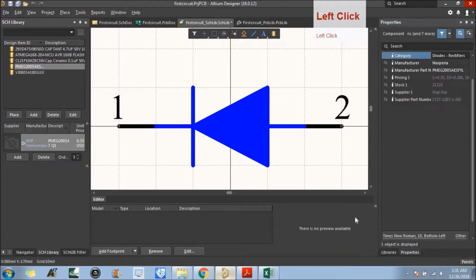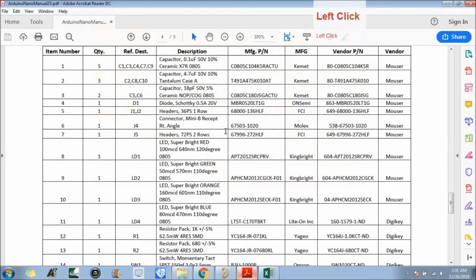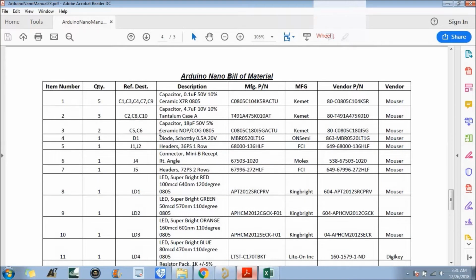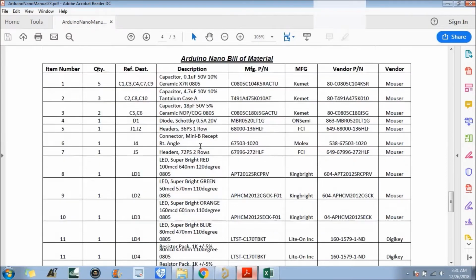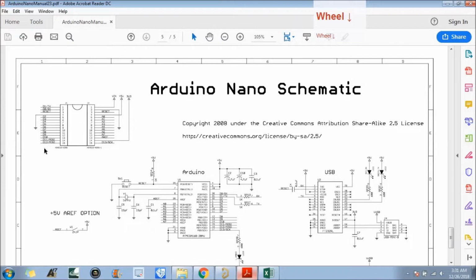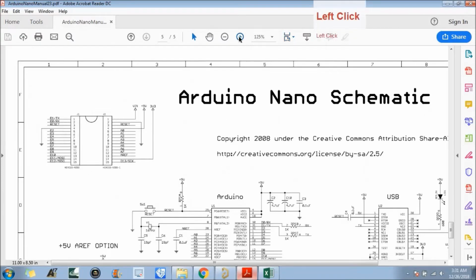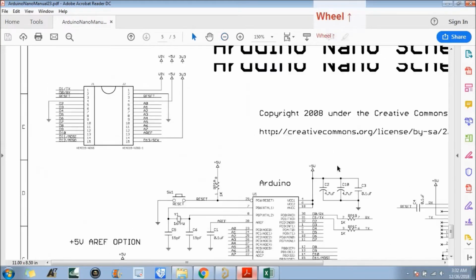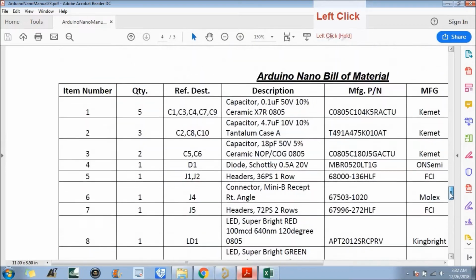So which is a 36 pin 1 row connector, J1 J2. Okay, so this is the connector that we are going to create the symbol for. There are basically 36 pins, and we need to divide each pin. So here I'm not going to create the 36 pin connector in whole. I'm just going to create an 18 pin connector, because these are the J1 and J2 two components.